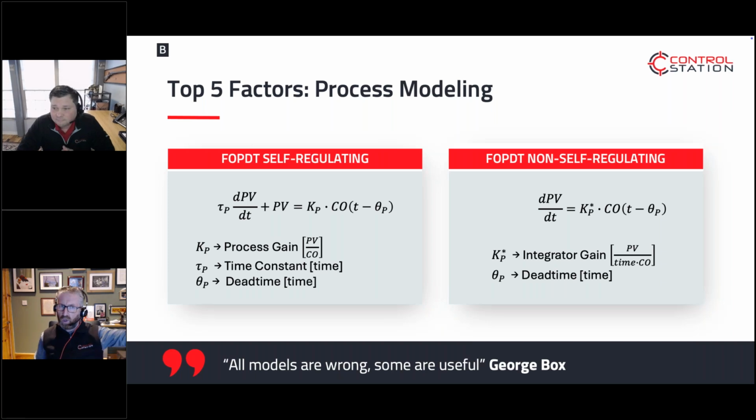If you've answered all those questions at the start or filled in that information, when you get to this point, you're going, okay, I get this now. I have information now. I know how I wanted to use it. You know, the gain, time constant, dead time, that ratio, you've been looking at first order model generation all of your professional career. If you've ever looked at a trend, the information is in there. You just need to watch for those sharp output changes and see what the PV does with that, to look for those relationships.